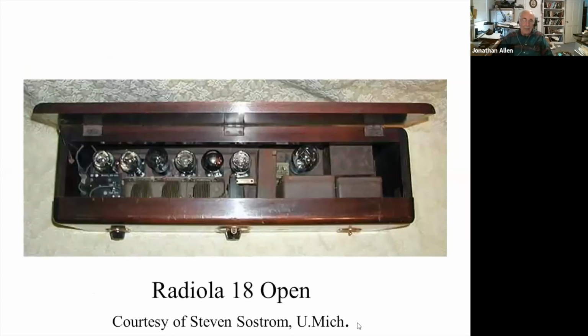But first, here's a look down into the Radiola 18. You can see these 3 tubes of the TRF stages. Here's a 3-gang tuning capacitor that drives them. And here's a detector, audio amplifier, and the rectifier tube for the plug-in power supply.